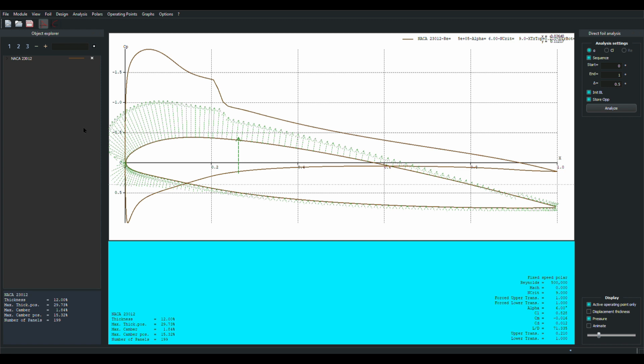So first of all, most important thing, remember that these curves are plotted inverse. It is negative going up and positive going down. And of course, we plot them that way so that we're not having to think upside down all the time. You know, that negative is good, it's lift. So this is the lift that's going on here. And any forces going out on the lower surface are counterbalancing the forces that are going out on the upper surface.